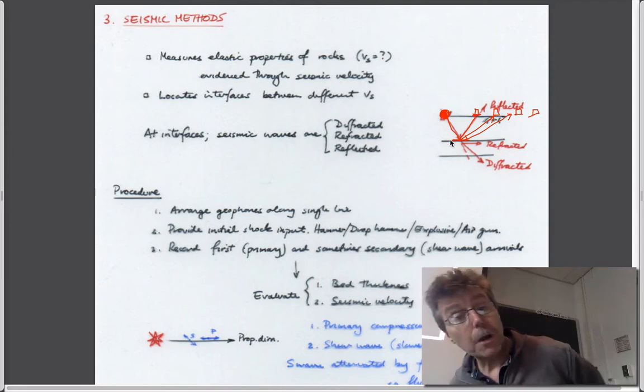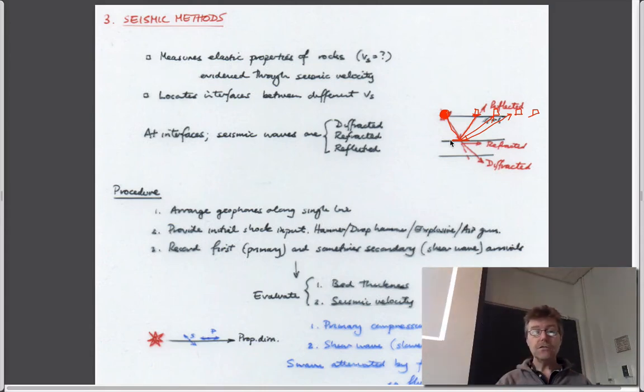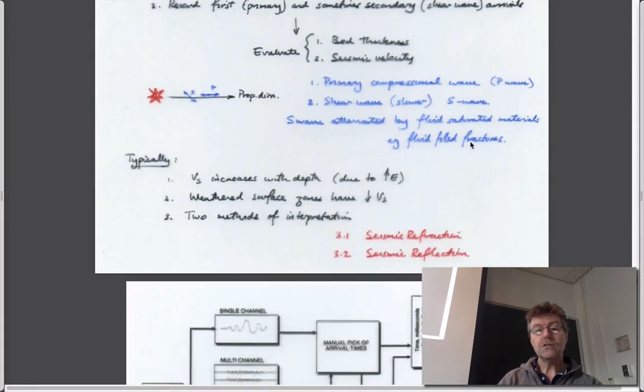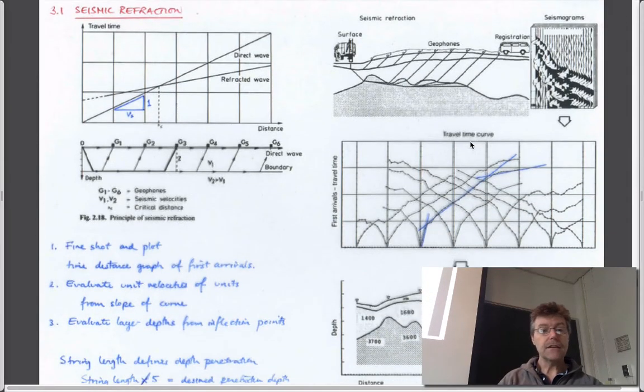And so just the geometries of how you might do it in environmental geophysics is that you can use either reflection geophysics, which is basically what this is, just like radar, no different, where you get the reflected wave, or you can use seismic refraction, where the idea is that you put some energy into the ground here. This has a wave velocity on the surface and a wave velocity below it, which is different.